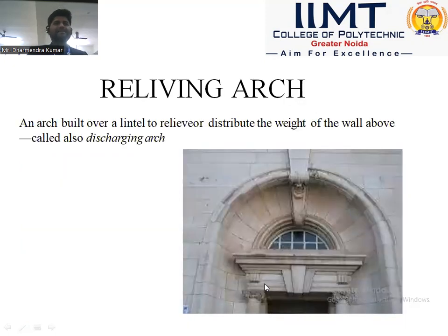Next is the relieving arch. You can see the relieving arch. It is an arch built over a lintel to relieve and distribute the weight of the wall above, also called a discharging arch.